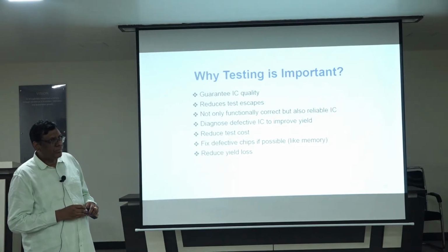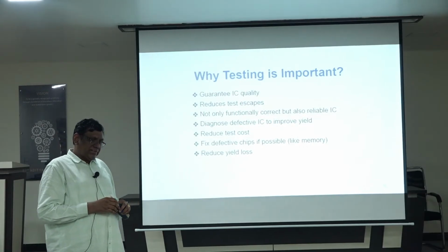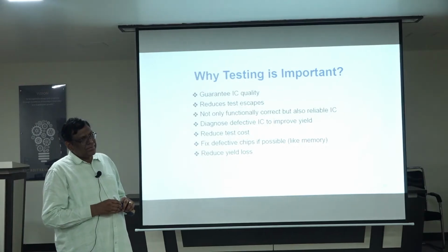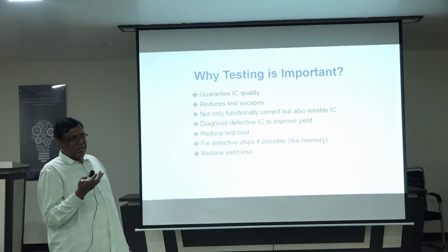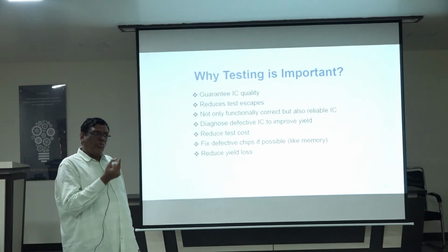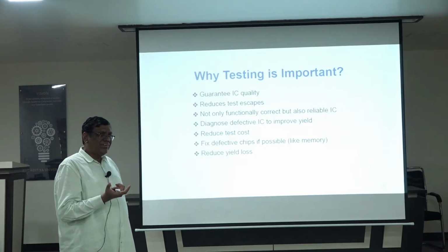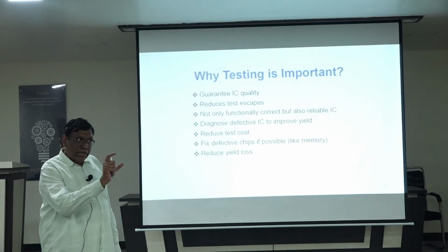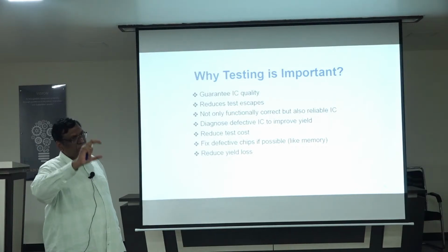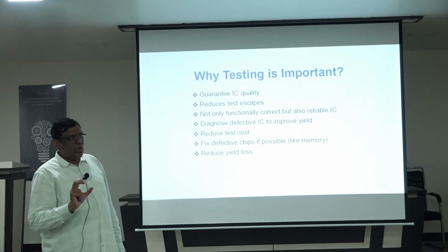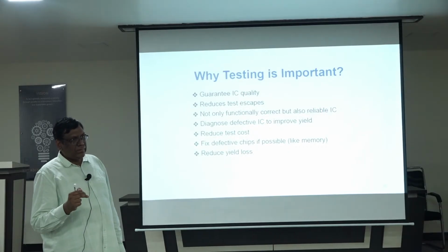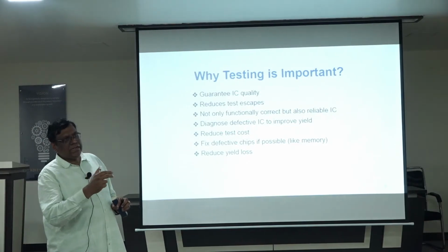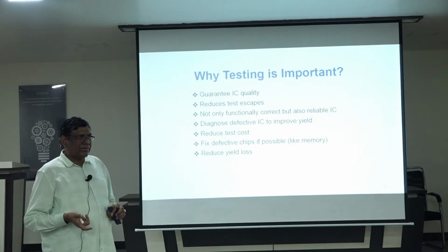Generally, we used to say memories in bytes, gigabytes, megabytes. Yes. So how can extra rows and columns contribute to the repair of single cell damage? Even if it is gigabytes of memory, a few bits can be corrected, no? That means we generally use 8 columns and multiple rows. Yes, multiple rows, correct. So on the hardware itself, extra spare rows will be provided. Extra memory will be provided. It is used only in the case of failure. In the general case they will not use it. It's like a spare, they will leave it. If the chip is failing, then they will try to repair it and deliver it to the customer.